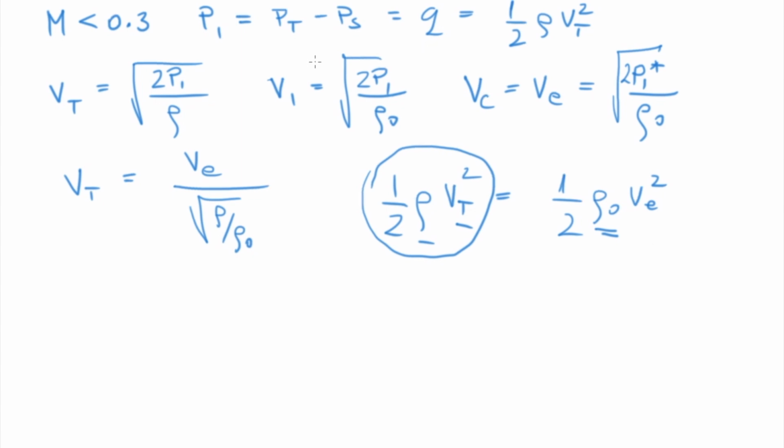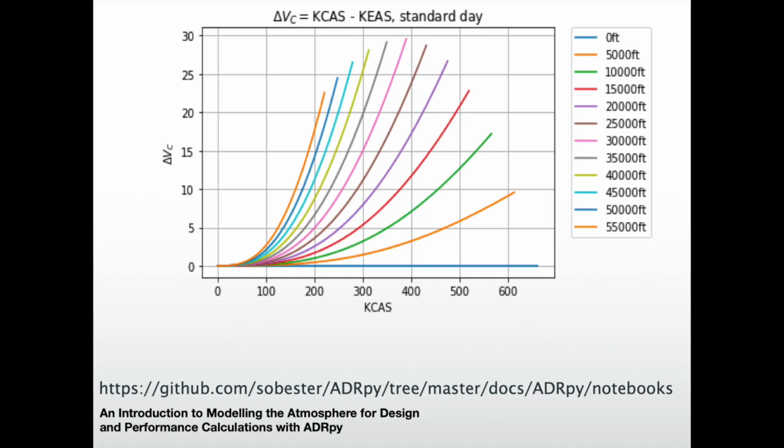The fact that a typical basic airspeed indicator is really just a dynamic pressure gauge is no particular hardship, because most of the really important stuff in the mechanics of flight, for example, the amount of lift an aircraft is capable of generating, is really a function of dynamic pressure rather than speed per se. Similarly for drag. The answer depends on how high and how fast you're flying.